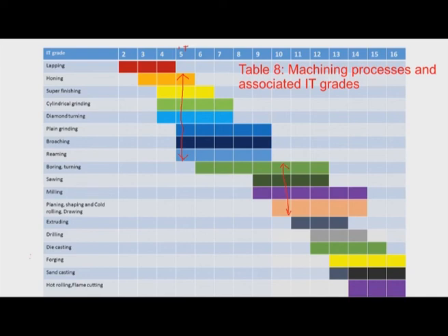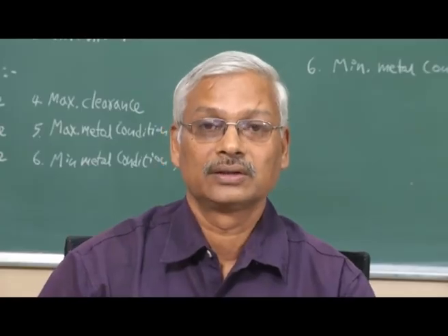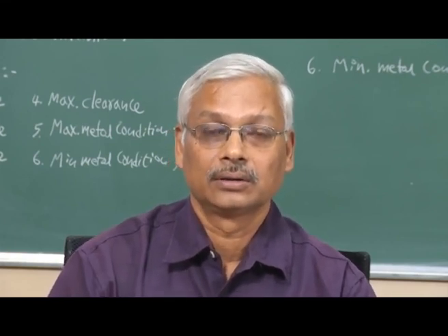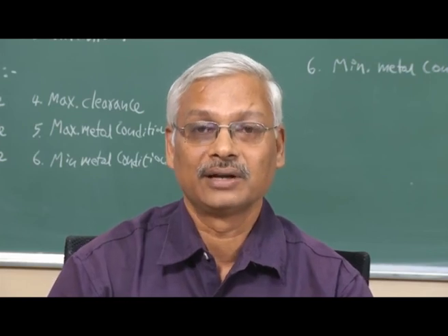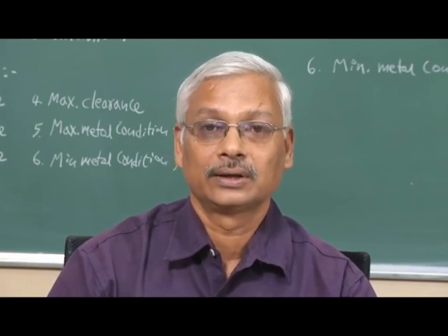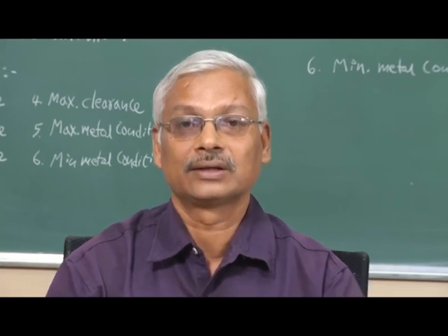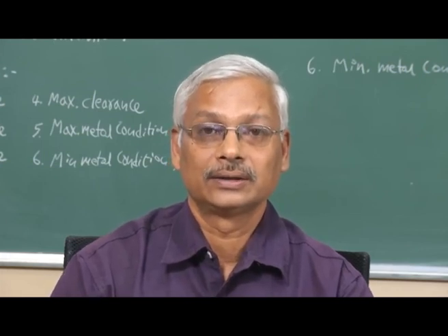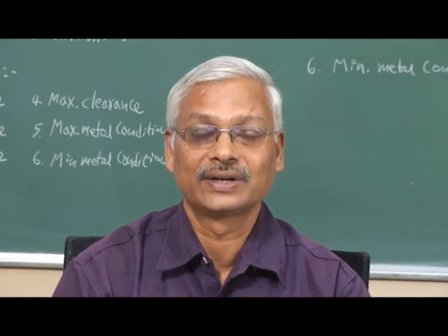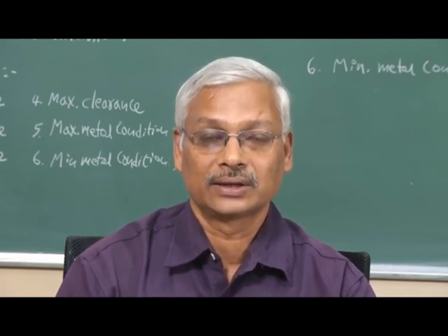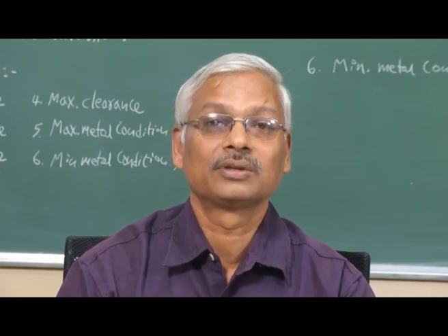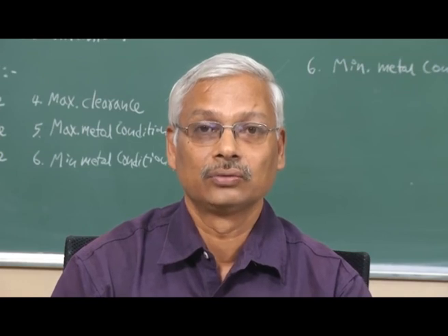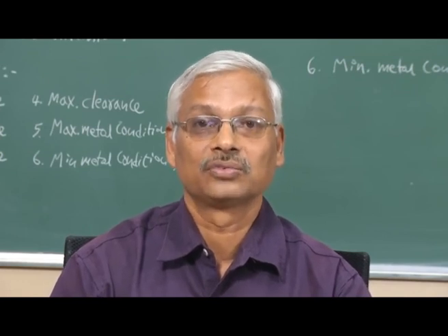Now we will conclude at this point. In this lecture we studied the various ready-made tables and charts using which we can find the tolerance values to find the upper limit and lower limit of shafts and holes. And then we studied the different IT grades and the applicable machining processes suitable for various IT grades. In the next lecture we will continue with some numerical problems. Thank you.